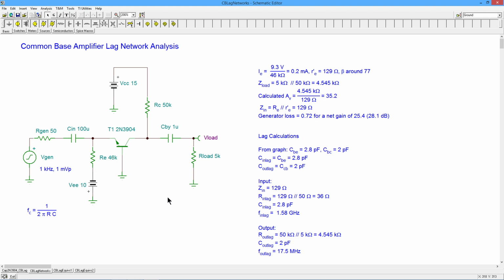So we just have to take this as it is. Normally with typical circuits, you don't run into that issue. This is the one that's going to be the dominant network. And to be honest, if you were really looking to get frequencies up here, you wouldn't be using a 3904. It's just not made to do that. The transistor is not designed to be working up at those frequencies. Okay, so I think that pretty well covers it.